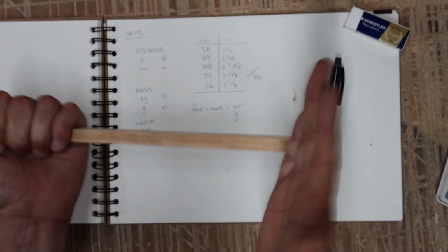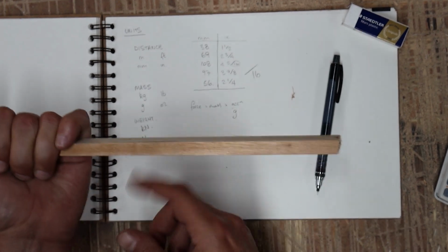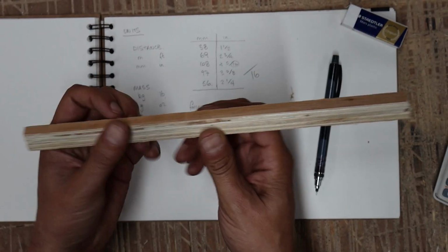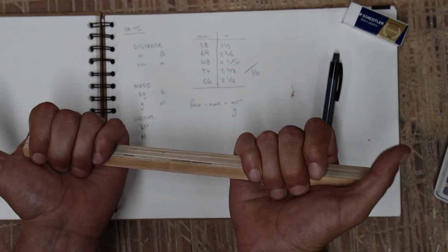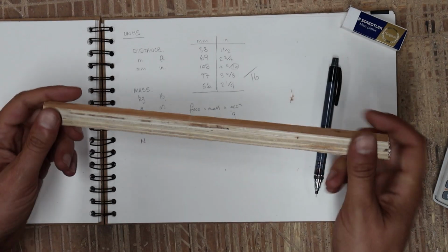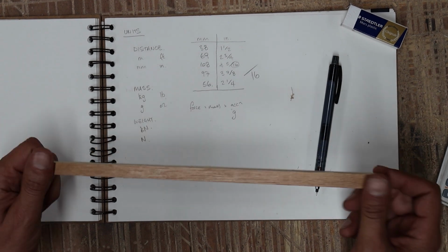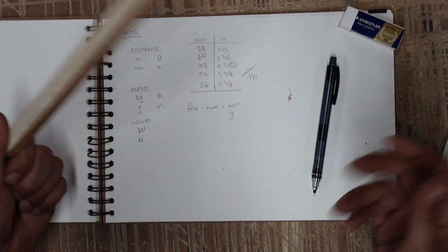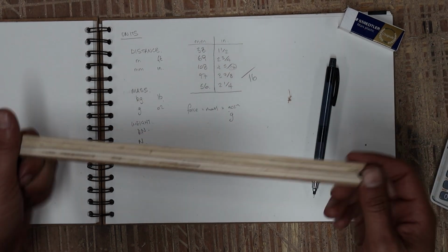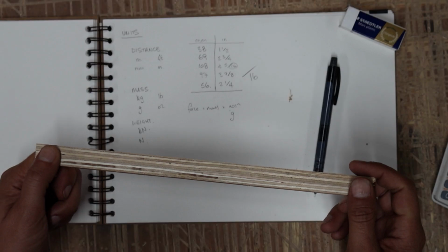And by logical extension, if we doubled the cross-sectional area, so this thing was twice as thick, then with the same force, we would be achieving half the stress. And that's how it works. And that's generally how we rate materials. Like, you've probably heard tensile strength or something of that equivalent. And you can compare different materials with that number.